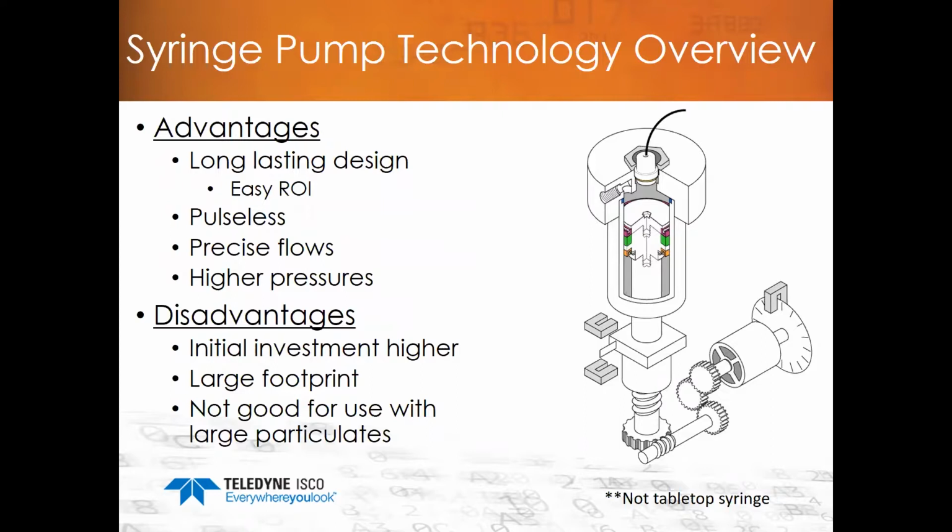Disadvantages, like we spoke about earlier, the initial investment is higher when compared to other pumping technologies, but the ROI is satisfied very quickly. Many times they're larger pumps, not like your smaller tabletop ones. And the preciseness of flow from a syringe pump is often dependent upon the smoothness and the fineness of the inside of the syringe cylinder.